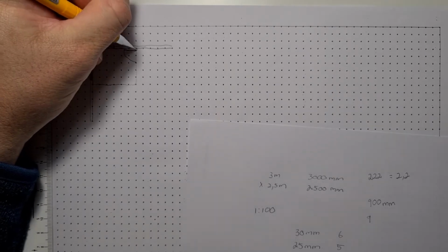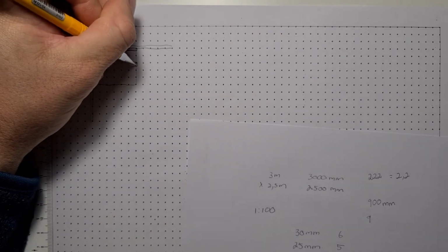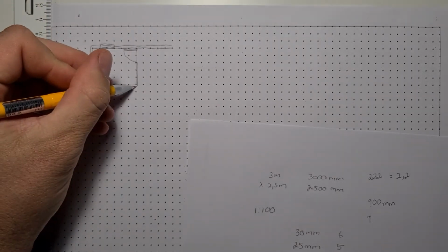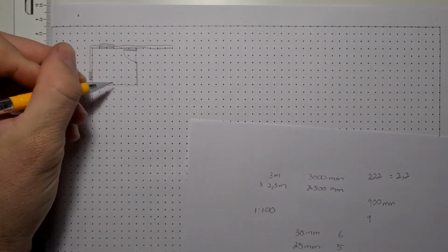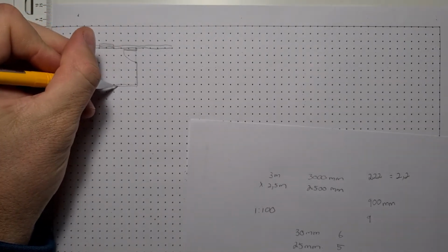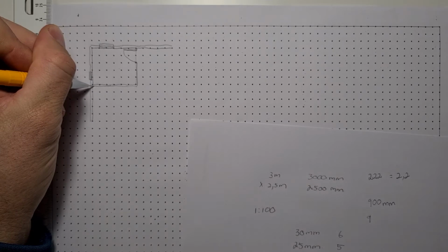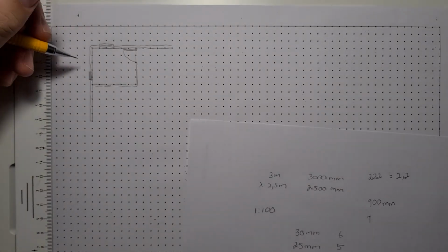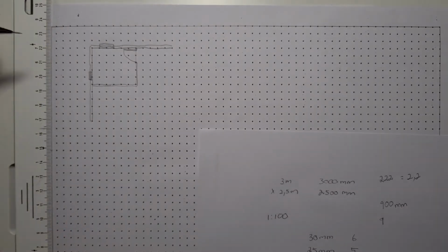So now you need to draw in your internal walls. So I'm drawing it in over here, the internal walls. Right, like that. So the next step is after you've done all your windows and doors. Remember, I'm only doing a little part of a floor just to show you how to do your actual floor plan for freehand drawings.